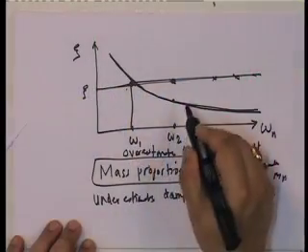Let us take a structure. A structure is being subjected to arbitrary loading. I assume damping to be mass proportional. If I assume damping to be mass proportional, I can only fix it in one mode, and that typically is the fundamental mode, because that has the largest value. So, I fix it there. Then what happens to all the higher modes?